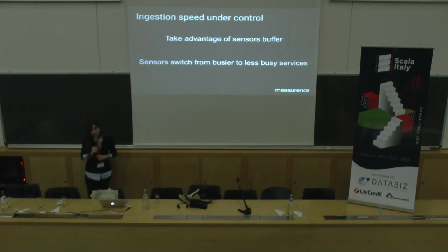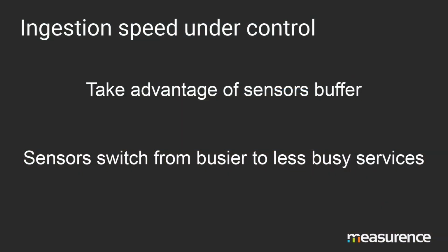In this case, thanks to back pressure, the sending rate will progressively slow down, thus giving a breath to the downstream computation unit. At the same time, sensors are constrained to send less data, and we risk losing some information coming from the sensors. However, this can be controlled by instructing the sensors to retain the surplus information in their own built-in buffer.